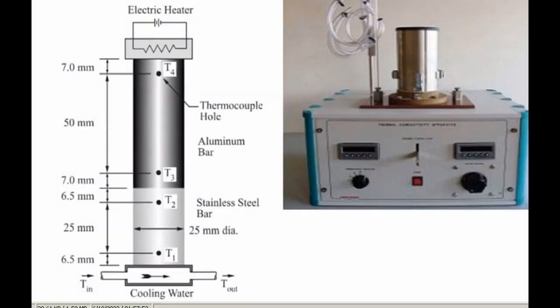When we take the readings for the very first attempt, we operate the water outlet line at the fully open condition. Previously I mentioned that we have attached a regulator, or in other words a valve, to the water outlet line in order to regulate the water outlet flow. We give water at room temperature to the equipment, and that water captures the heat passing through this combined material.